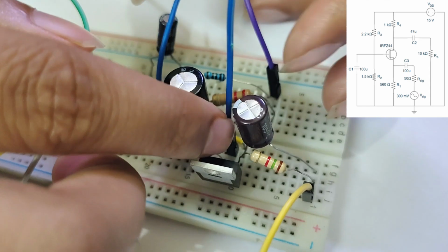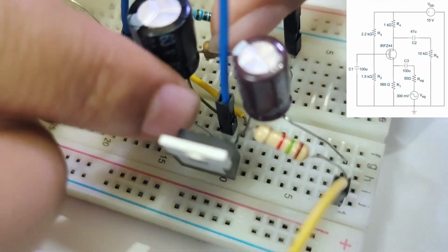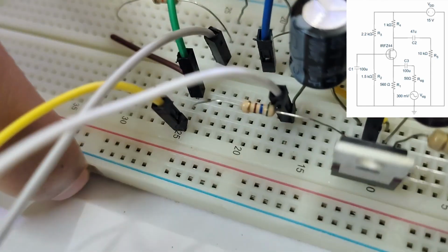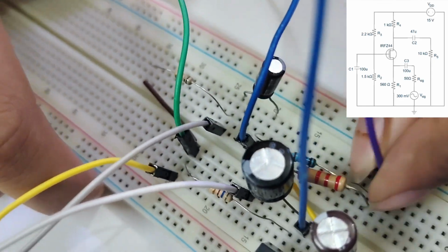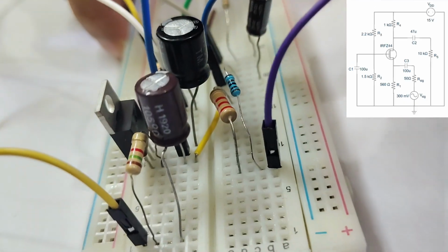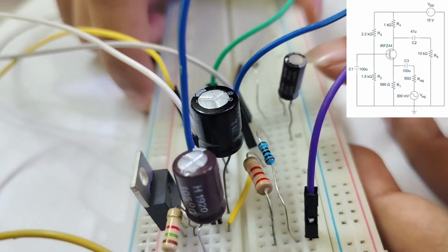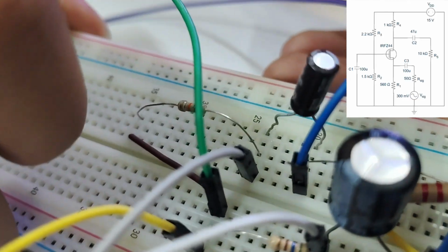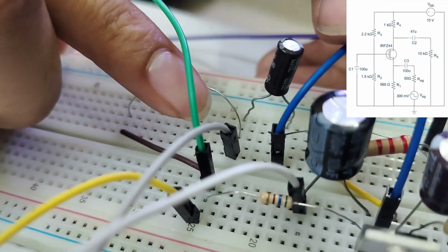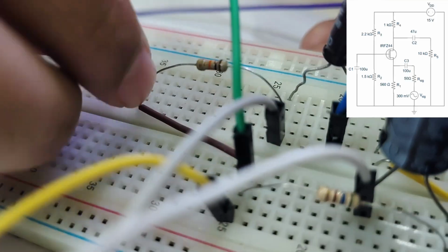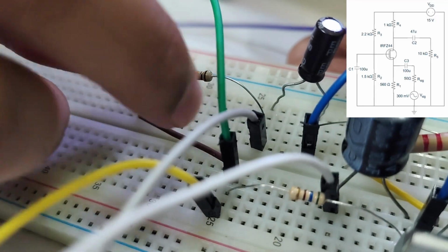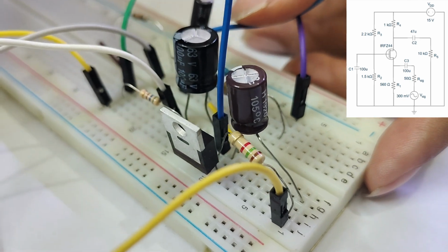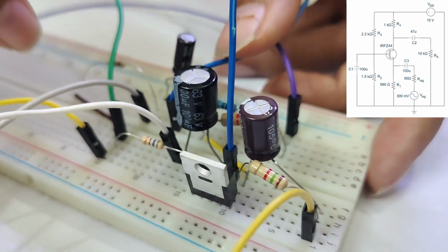Then we have connected this jumper wire from drain to this point, and we have connected these two resistances here. Then we have also connected this jumper wire, which will act as a DC biasing node. Along with that, we have here this 47 microfarad capacitor, which will act as a bypass capacitor, and we also connected this high resistance that will be used as an output resistance. We will measure output voltage here. So that's all, and now we will see the frequency analysis of this input and output voltage.